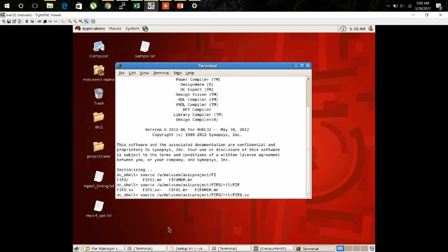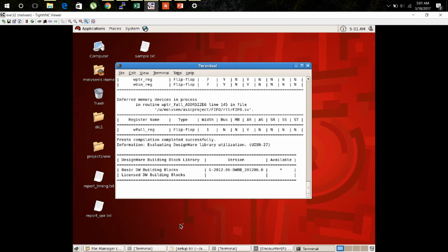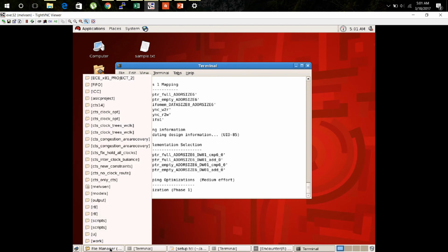So this is the SystemVerilog, the RTL code for the 5.4 design. So I need to run the corresponding Tcl file which converts the SV design into a netlist. The Tcl file is present in this folder. So I source it, I run it. While it is running, I will have a quick go through that particular Tcl file.